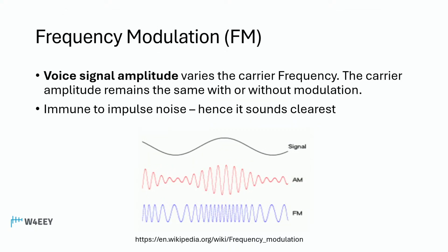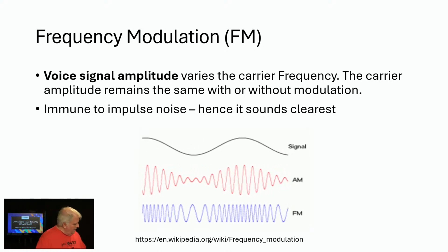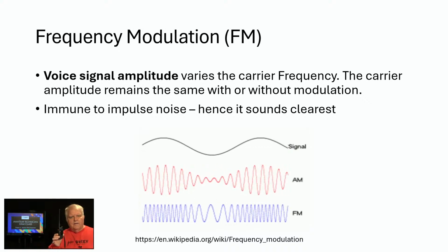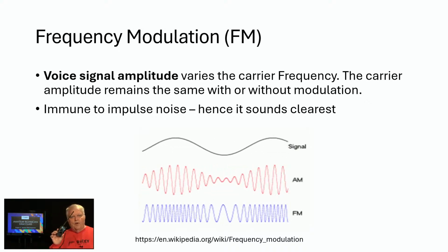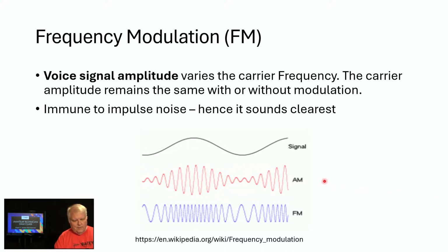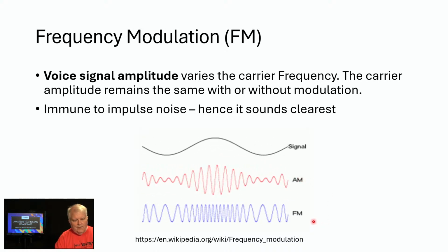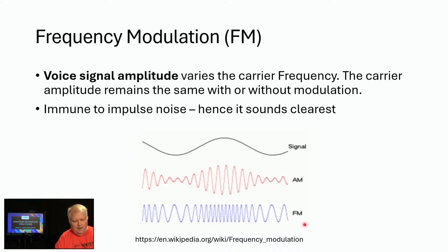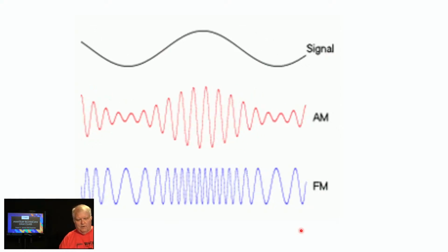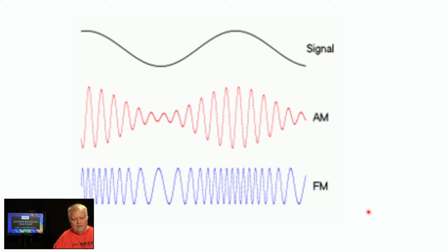All right, let's move on to frequency modulation. For the little radios, like technicians will typically start out with, the little handy talkies, these are FM, or frequency modulated radios. In here, this was the amplitude modulated signal we saw before, where the signal strength is changing. For FM, the signal strength stays the same. It is the frequency of the carrier that is changed. And I have a little bigger slide here you can see, maybe a little easier. This is an FM, or frequency modulated signal.